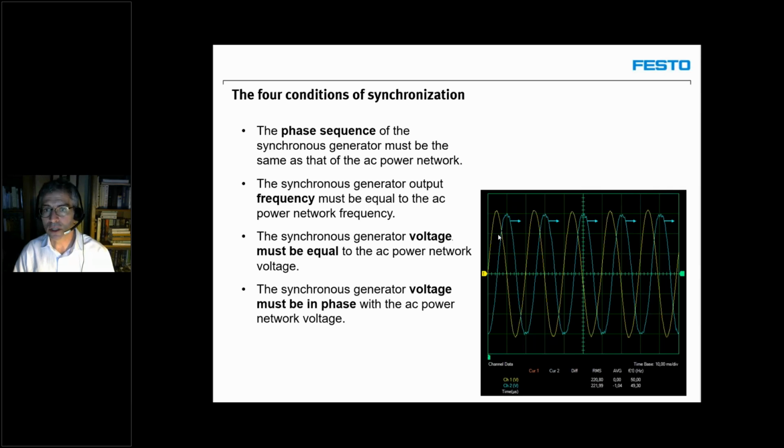And if I was to close the switch with a real generator, a megavolt-ampere generator weighing multiple tons, in this condition where I have about a 90-degree phase shift, the generator would just explode. Of course, the mechanical stress on the generator would be much too high, as we will see in a moment. So we have to make sure that in the oscilloscope view the two curves are on top of one another before we close the switch.